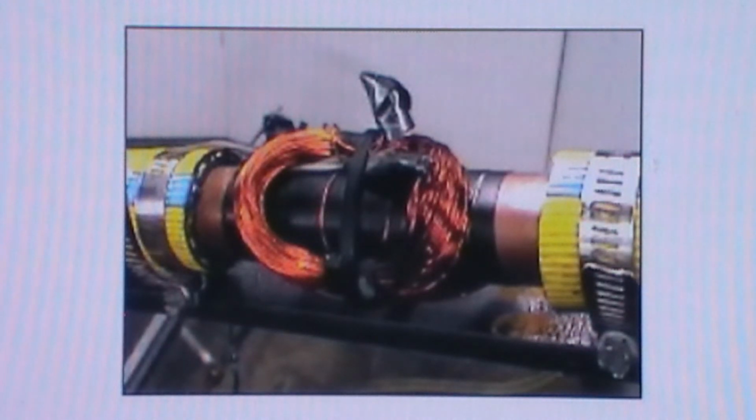The signal is fed into a LED audio level display driver. The LEDs were calibrated by pressurising the less than full water storage tank with air, then opening a gate valve, allowing water to flow past the impeller until a 10 litre volume had passed through. The time for the event gave the number of litres per second. Water speed through the 12.4mm inside diameter water laser tube could then be calculated and attached to the final LED illuminated.